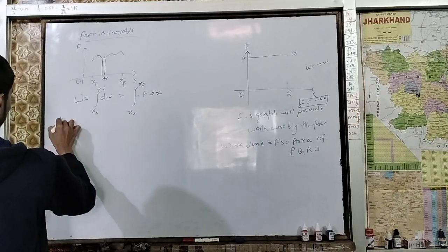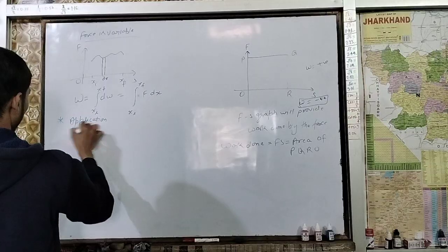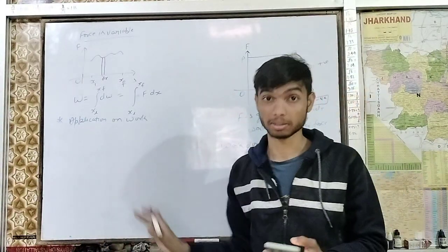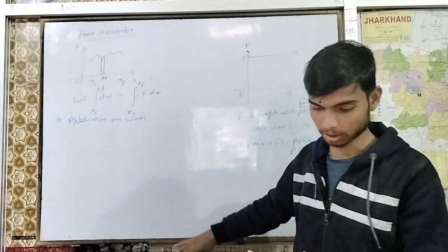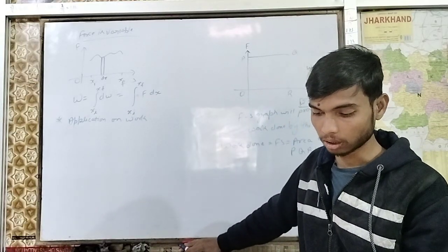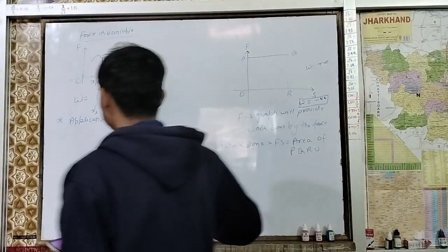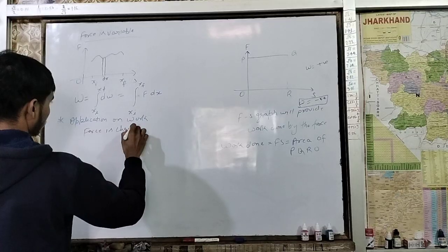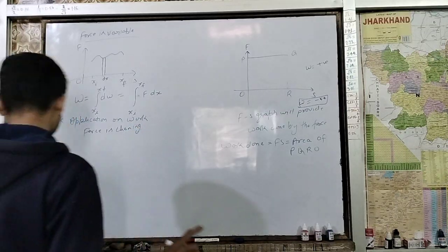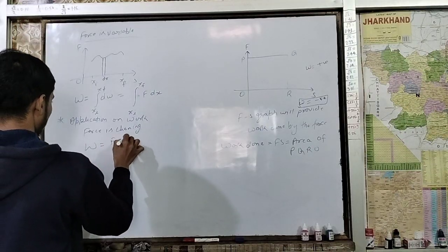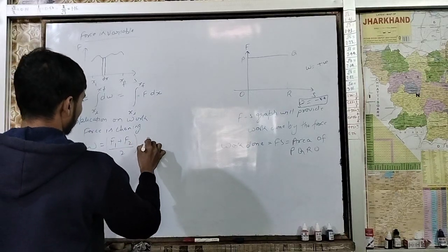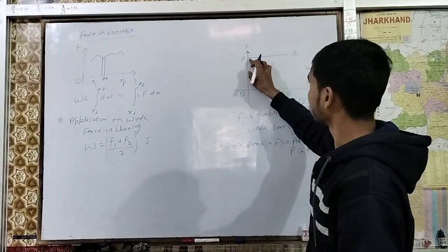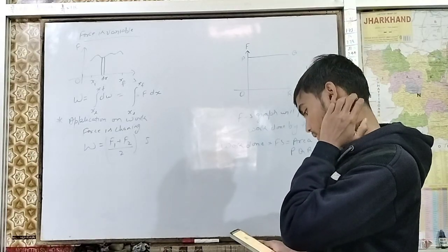Application on work. First point. If a force is changing linearly from F1 to F2 over a displacement S, with respect to displacement, then our work done will be (F1 plus F2) upon 2 into S. This equation will be used.